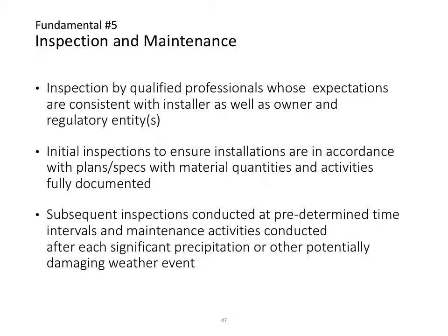We want to have someone there as a certified professional, or at least someone very familiar with the products, the goal, and the owner's goal of the site, to ensure the contractor is doing everything according to the plans, specifications, and drawings, and also getting the right material quantities and not skimping on materials or cutting corners, like on the fence. That one with the wattle just didn't quite go all the way.